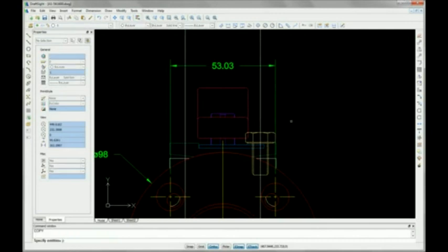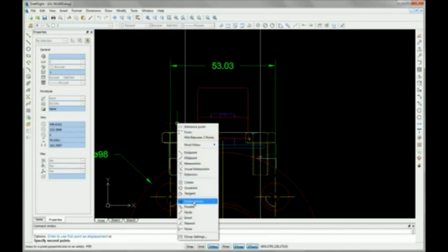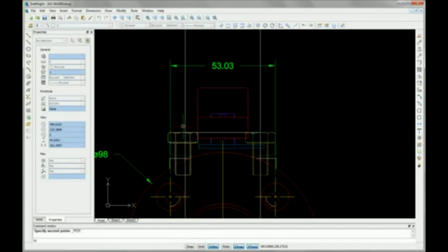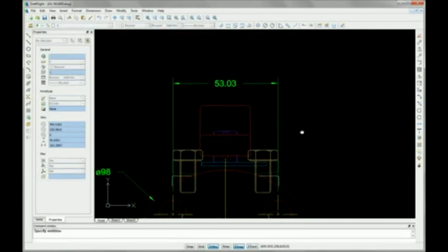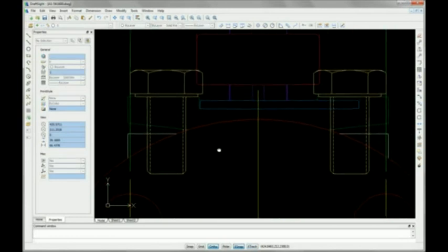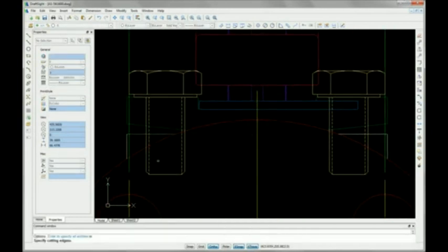I can copy my previous components like before, and to make sure I have the appropriate location, again, I'm going to use a specific snap in this case, perpendicular to that infinite line. I'm done with the infinite line and I can delete that, and I want to do some trimming here. The trim tools are easily accessible in a familiar fashion.